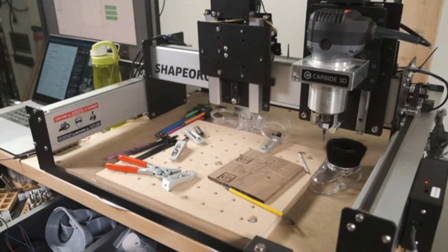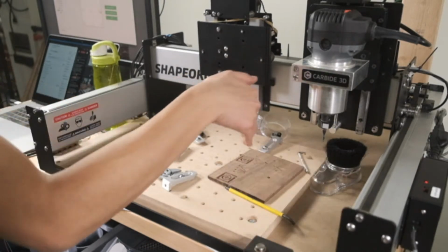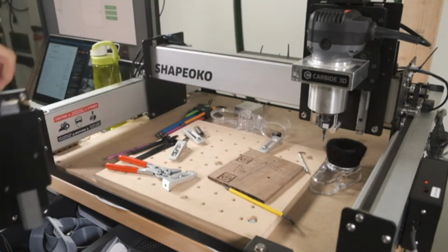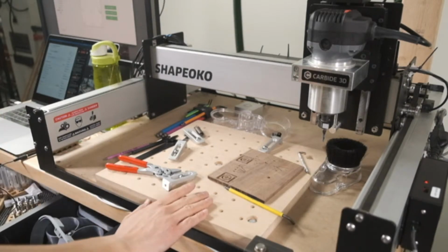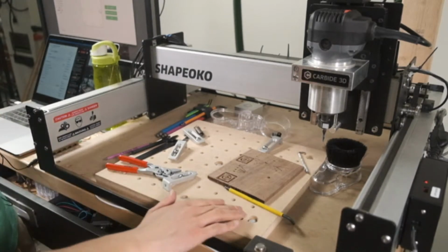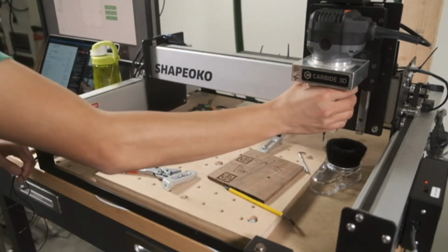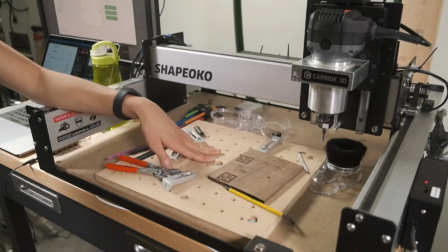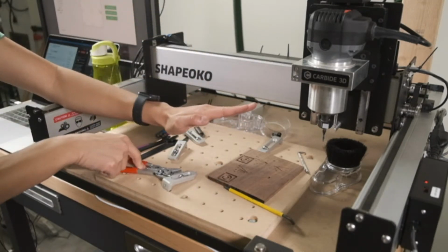Okay, and then I think the last thing to talk about is really just tramming. If your spindle isn't perfectly perpendicular to your wasteboard, you might get ridges in your cut. If you cut a pocket or you're surfacing your wasteboard, you might feel little grooves or scallops, and that's because the router isn't dead perpendicular to this surface. If you have a flat end mill that's crooked, one end is going to cut deeper than the other.